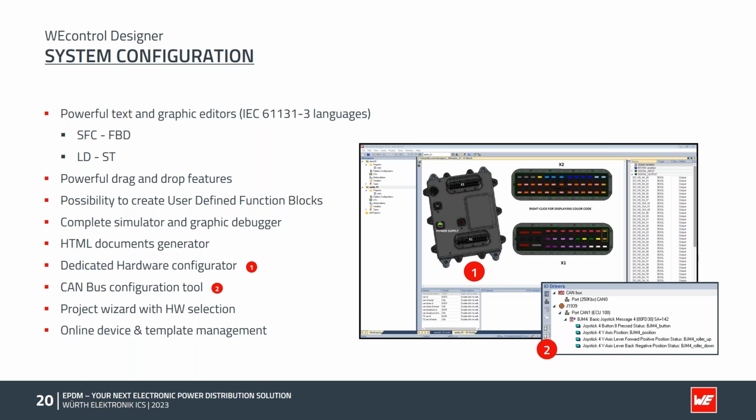And as you can see here, labeled with the number 2, we do offer as well a J1939 library. Just enter your PGN in the function and the matching SPN list will be displayed. You just need to select and give a variable to this signal, and you can use it in your programming environment.